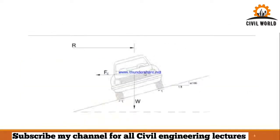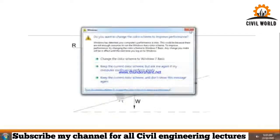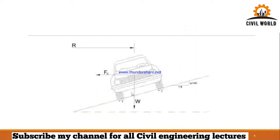The same vehicle is moving in a curved path, where W is the weight of the vehicle acting at the center of gravity, FC is the centripetal force because that is directed toward the center of the circle, and R is the centrifugal force, which is just the reactive force of the centripetal force. Our centripetal force is accompanied by this centrifugal force, which acts in the opposite direction to the center of the circle.